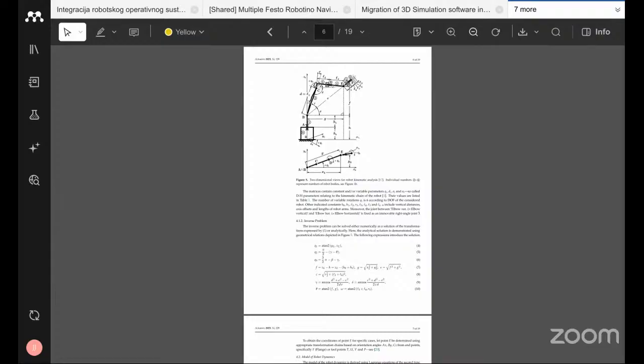So there is a point E, right? This is called the elbow reference point. This is for conducting the geometric analysis. So this is a reference point to conduct the geometric analysis. Then the base joint angle Q1. Q1 is equal to atan2(YE, XE).